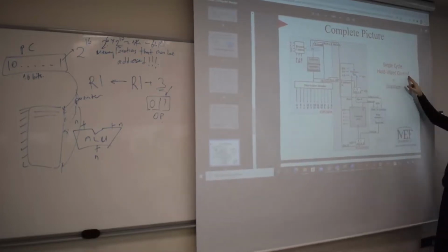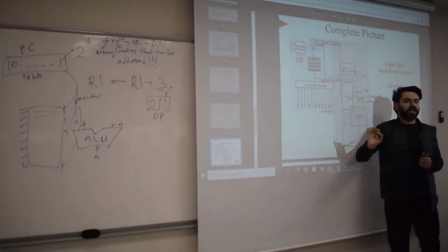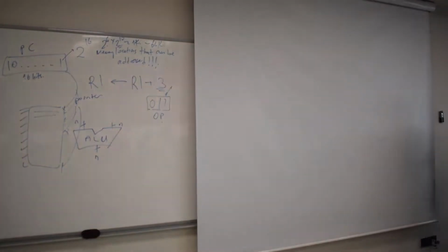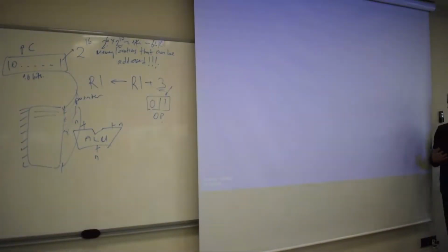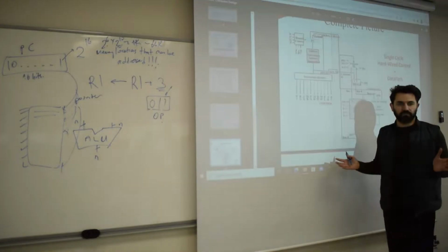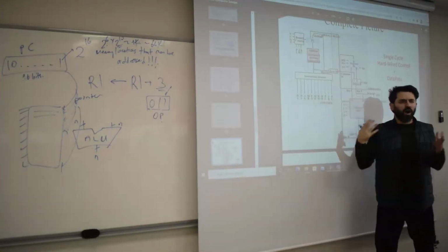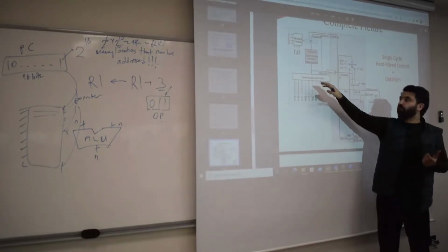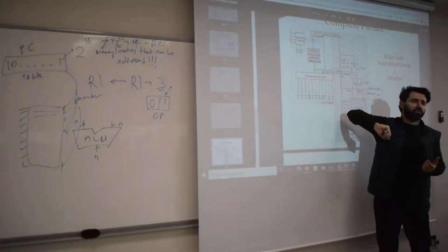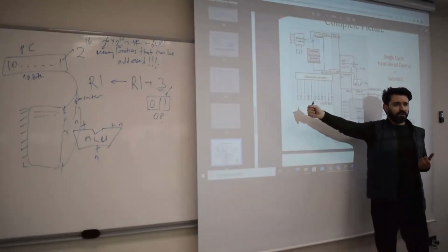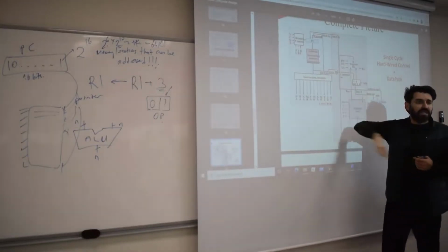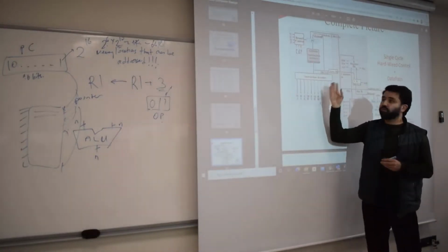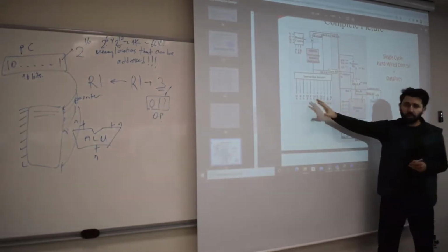What is hardwired control? That means the instruction decoder is combinational logic. It only contains memoryless elements, okay? No sequential logic. Why are we calling it hard then? Because when you design this, if you have, for example, an extra instruction you would like to put into your format, then it will actually change the instruction decoder entirely. Because you have to make up for that instruction, because that instruction will change some of the control bits.